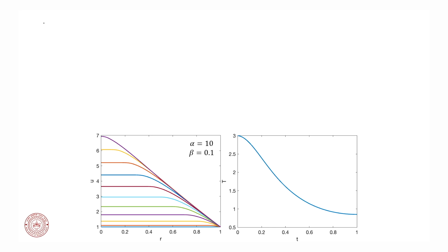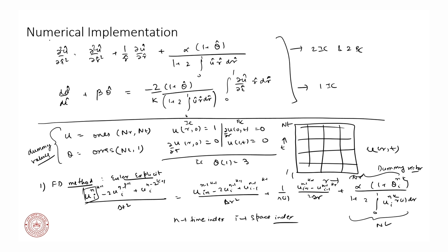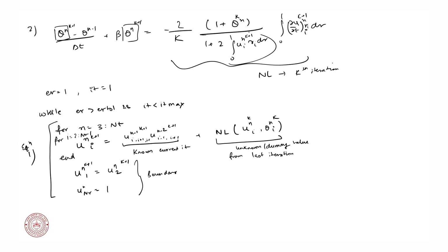Now, for equation 2, what we need first is to define this du, and then you can use your gradient between t and u. Again, u is a function of r and t, just make sure that you have taken a derivative along time and not along space. These integrals, I may have forgotten to mention even in the last set when we were doing the mass and spring, these integrals you can solve using the trapezoidal rule. So, you can use trapz in MATLAB and you can do this integration of u comma r. Alright, likewise over here you can solve these using the trapezoidal rule, you can use trapz. Likewise for this, trapz.